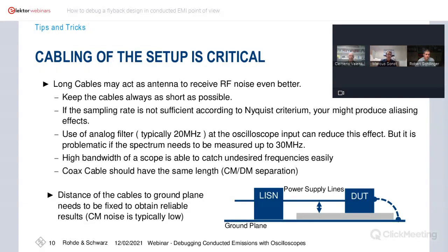So the cabling, as I mentioned already, is critical, and especially when you're using very long cables, you can easily create quite good antennas to receive any RF noise which is in the environment. So the recommendation is to keep the cables as short as possible. It's always good advice.